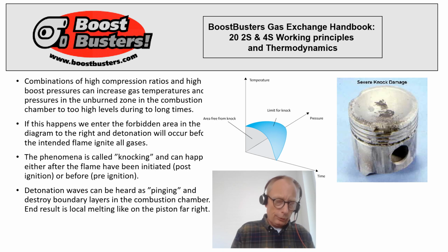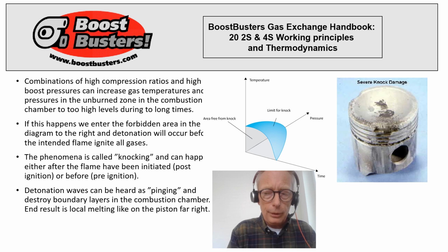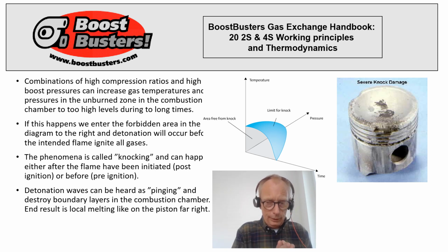If the temperature and the pressure in the combustion chamber becomes too high, it can self-ignite and come to detonation. Detonation is a combustion process which is much, much quicker than the combustion we planned for with the spherical flame. And the gases which are farthest away from the spark plug are subjected to the biggest risk for detonation.